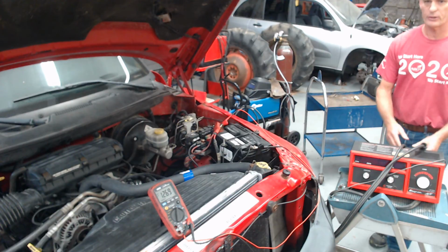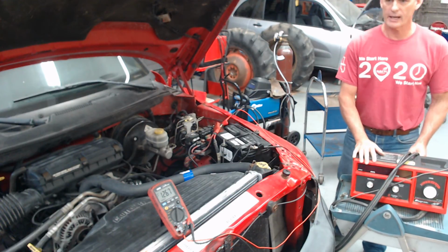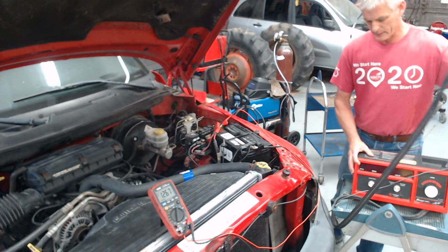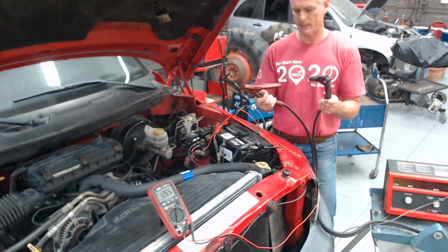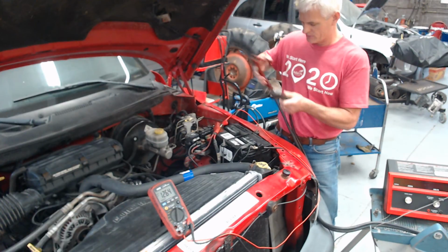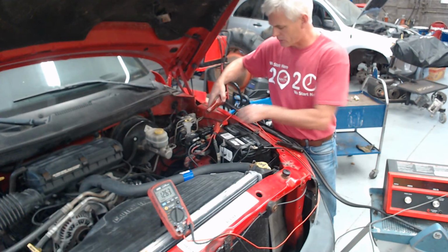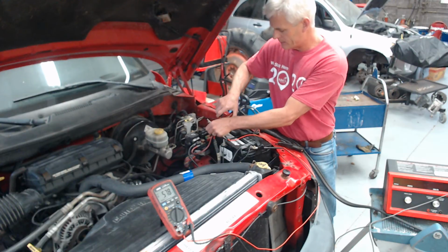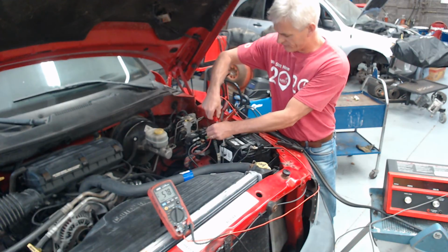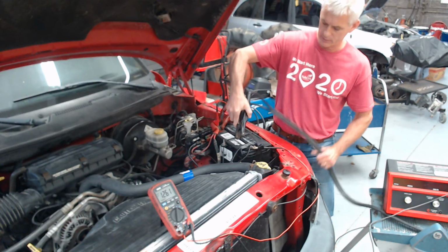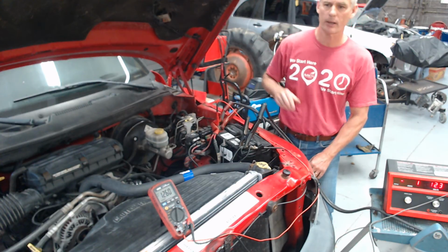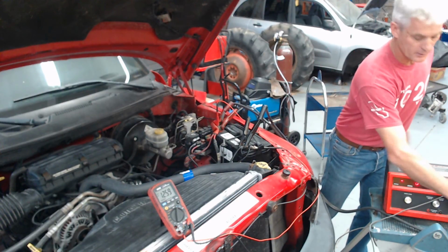And we're going to use this AVR, which is an amperage voltage tester. We're going to take what they call the internal 18-volt leads, these big, heavy red and black leads. We're going to go red to positive, black to negative. This is not a battery charger, and it's not a jumper pack, so it's totally safe to hook up red to positive, black to negative. You're not going to get a spark. You could potentially get a spark if somebody was over here cranking up the load.